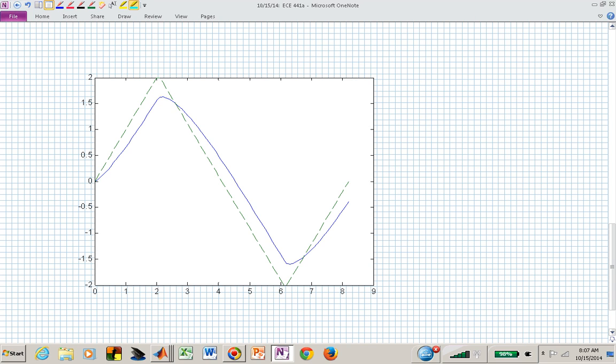Okay, so you're looking at the middle part of the decreasing waveform, and you're probably waiting until the transient has gone away. You have a transient every time you switch your reference. Do you see that? Beginning with, you have a little bit of a transient, and then you sort of get into this locked condition where you're tracking this dashed line. The dashed line is your reference. That's where you're wanting this, let's say, robot tool to go.